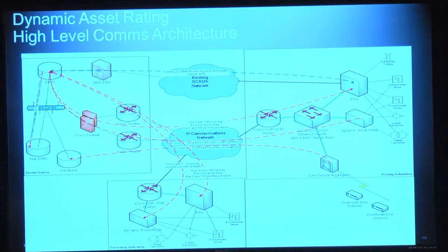So as you can see at the top half, I'll just go through this quickly, that blue line at the top is the existing UHF radio, UHF SCADA-based network, talking to an RTU in the field and continuing to talk out to all the individual devices. A clear rule or a mandate that was put on the entire project was that nothing is to interfere with that existing communication pathway. It must be all done separate to that.